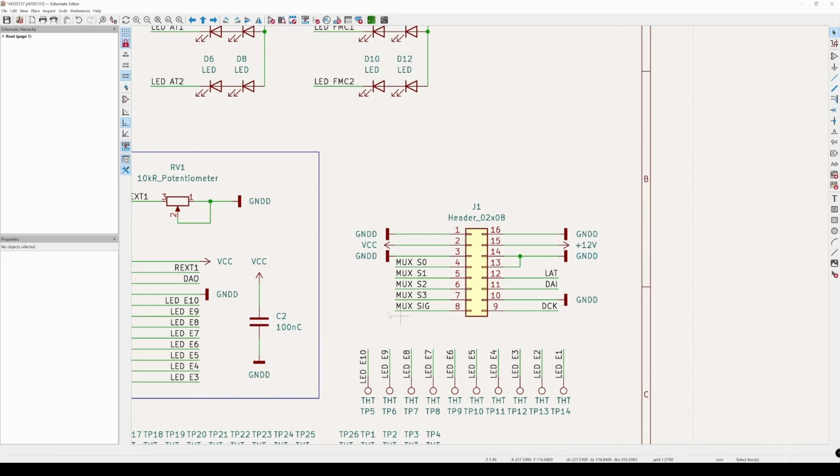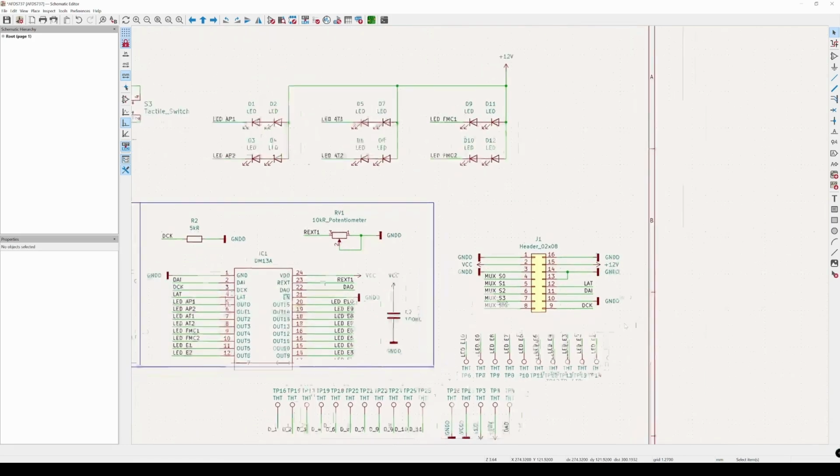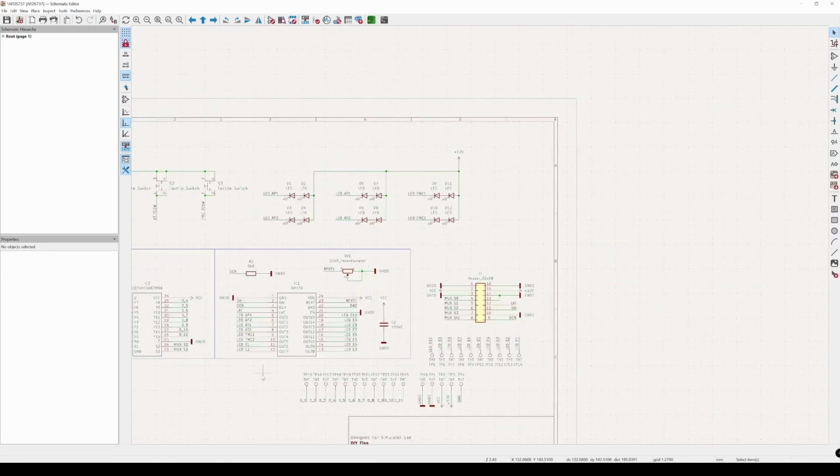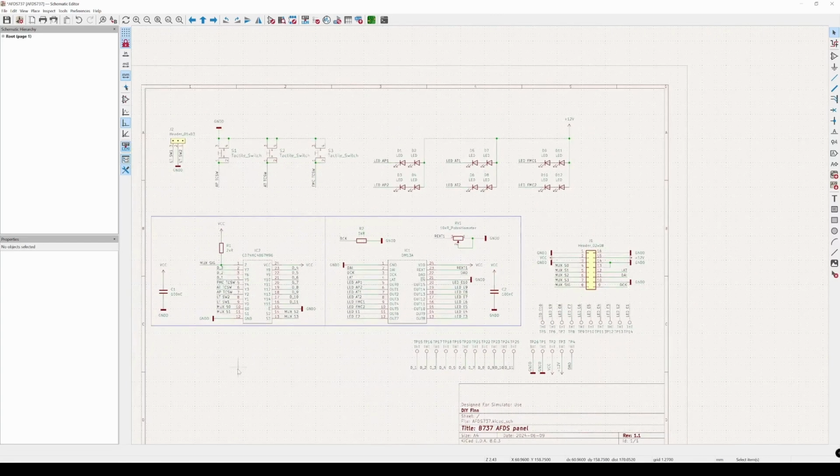And you might notice that I have also placed the grounds so that they are surrounding our voltage pins. That's in hopes of reducing noise, but that might not matter at all for your case or even for my case, since this is just a simple flight simulator part, simple IC, simple controllers.